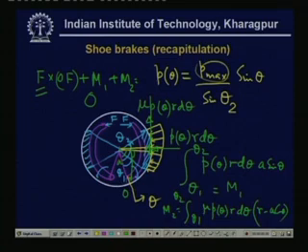Then another thing which is very important for design is that there are pins over here. You see there are pins where it is hinged. Now, the pin reactions will be present, and how to estimate these pin reactions? Those are coming from the force balance equations.